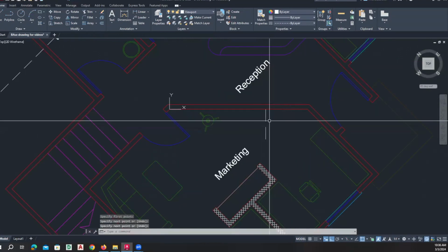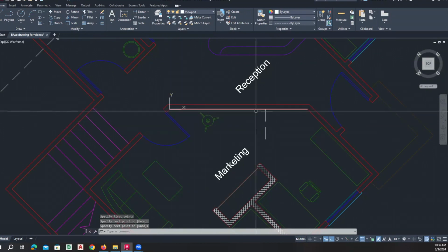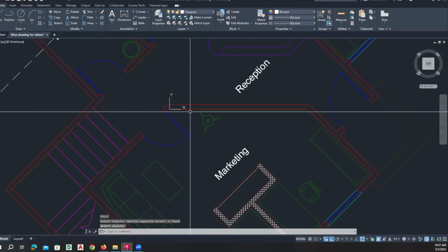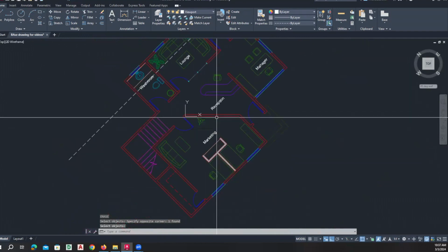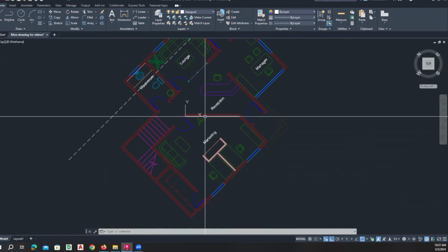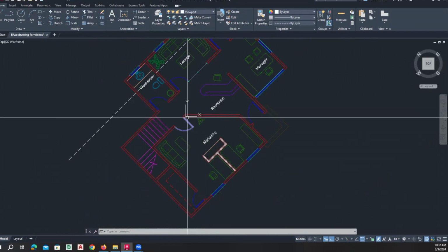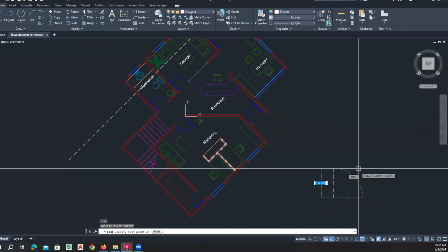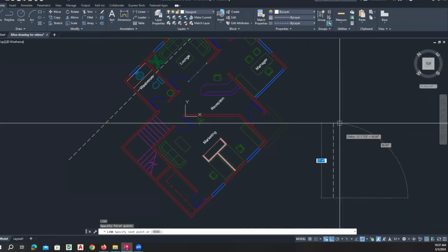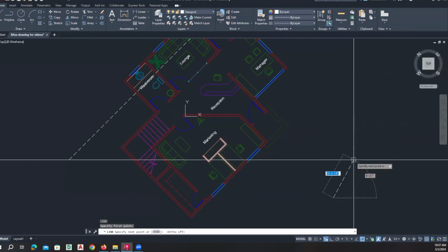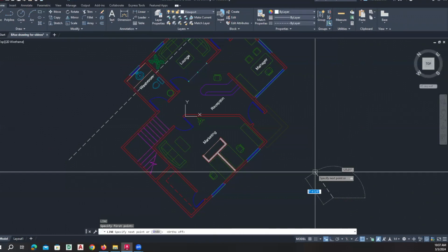And everything I draw is oriented based on this 45-degree wall as well as the UCS, right? So when I have things set to ortho, it is orthographic. It is ortho 90 degrees to my UCS. So if I were to draw a line now and I turned on ortho, it is parallel to that UCS. If I turn it off, I can again draw it however I want.